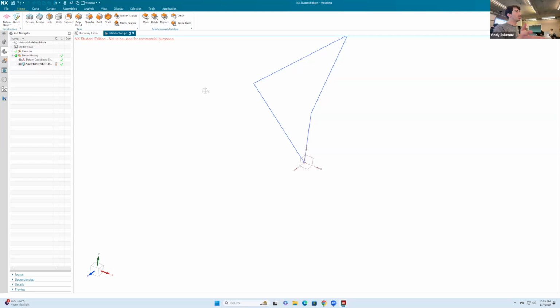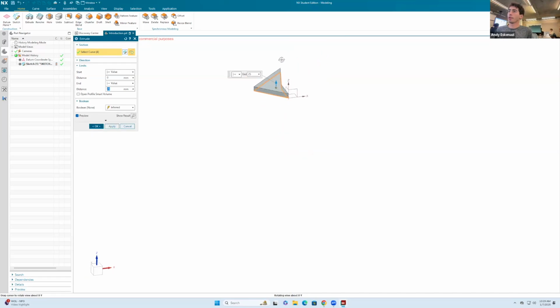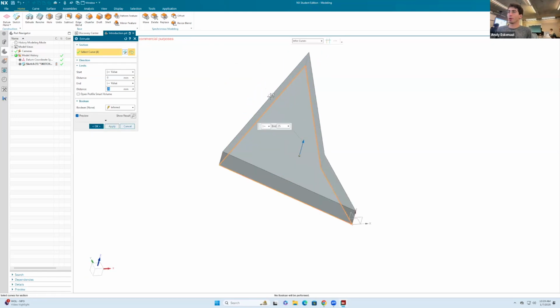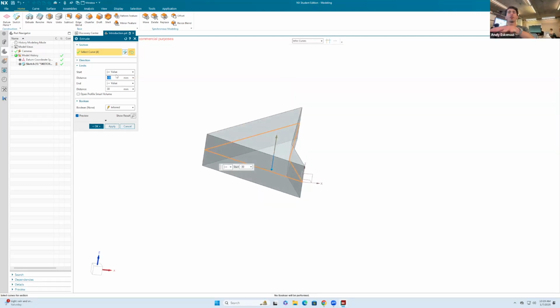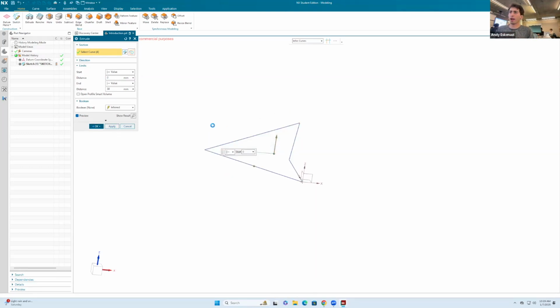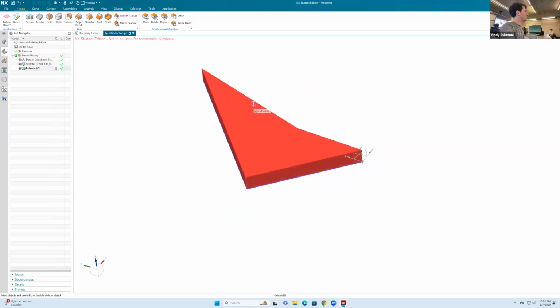So now that we have this very primitive shape, let's give it some volume, right? Now it's in 2D, let's make it 3D. The most intuitive way of doing that is with the extrude command in here. It's telling you to select the curve, so I'm doing that. I can hover around by clicking the button of the mouse. Let's say I want to give this 300, or let's give it 30, for instance. I can also say that I want this to be negative 30. That way you see there's a lot of freedom in how you define the extrusion in particular. I'll say just 30 here for now. And voila, now you've created your first shape in here.